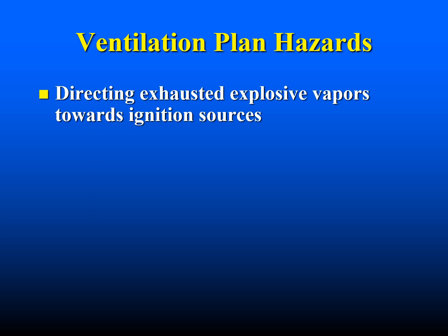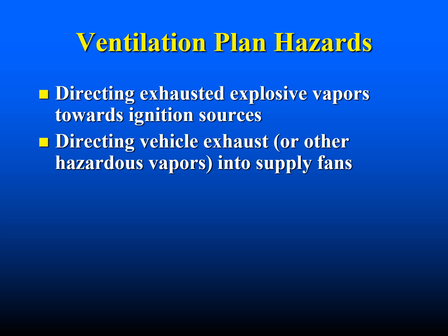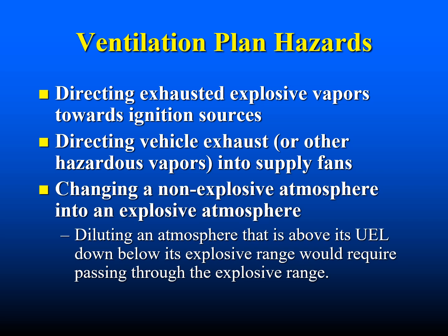Let's take a look at some of the ventilation plan hazards that we have to consider. Directing exhausted explosive vapors towards any ignition sources, directing vehicle exhaust or other hazardous vapors into our supply fans, changing a non-explosive atmosphere into an explosive atmosphere, diluting an atmosphere that is above its upper explosive limit down below its explosive range would require passing through that explosive range.